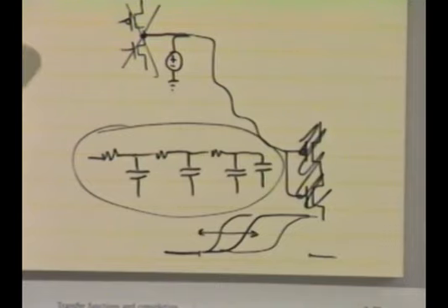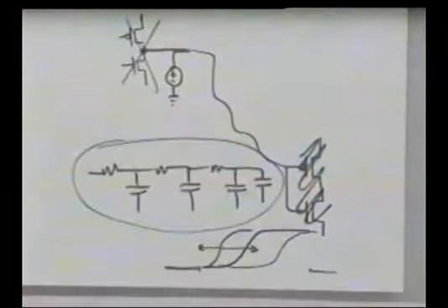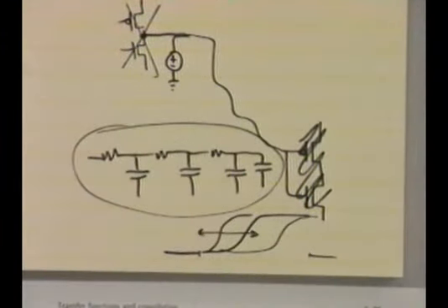Whether it can clock at 300 megahertz or 450 depends on the delays. For a whole bunch of the wires, doesn't make any difference at all. It's not critical. If it's delayed 8 nanoseconds, 15, doesn't make any difference at all. For some wires in an integrated circuit, known, of course, as the critical path, right? These are the wires that limit the performance, okay?